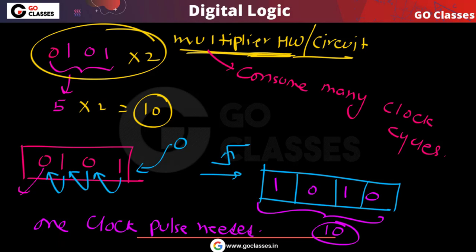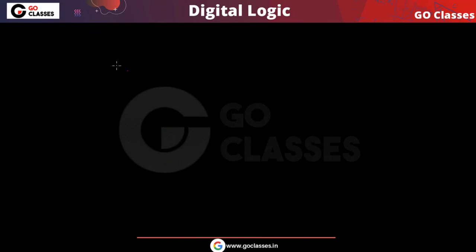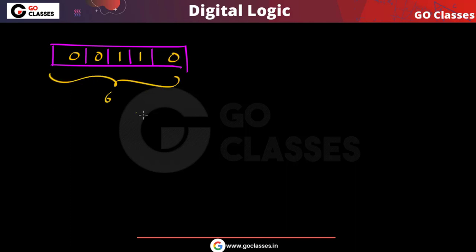So this is the application of registers. I can say that this left shift register, sorry, I said right shift earlier, you can use for multiplying with 2 power k. Let us assume that you have this number, this is your data, 0 0 1 1 0. This is 6. You can note this is 6.